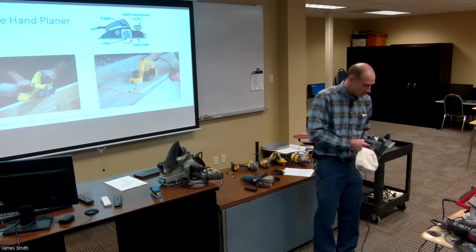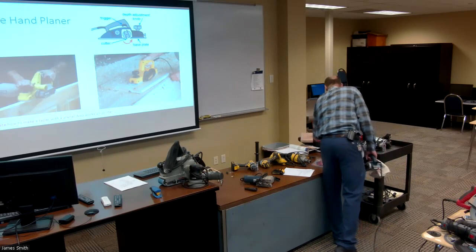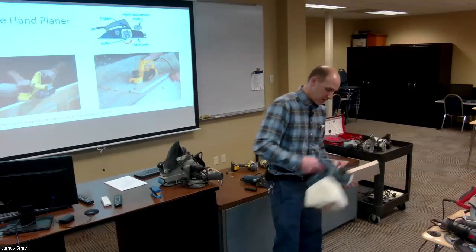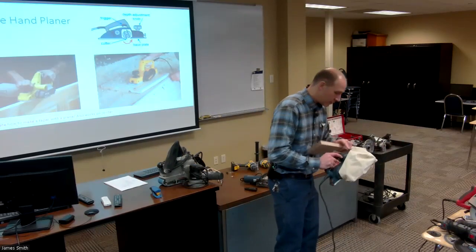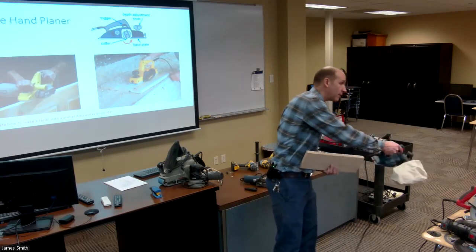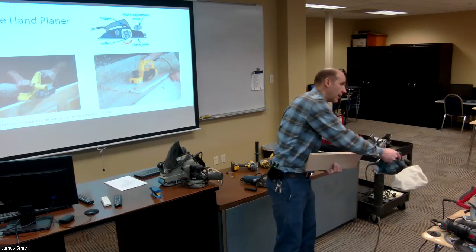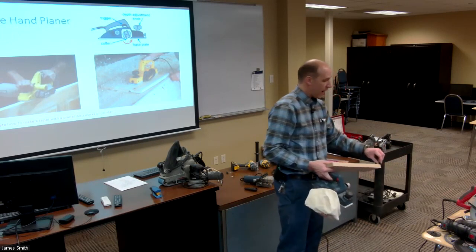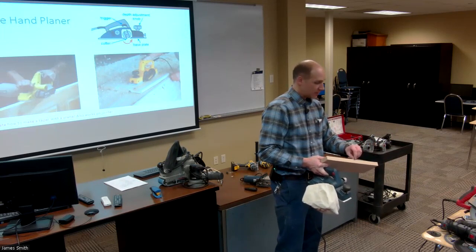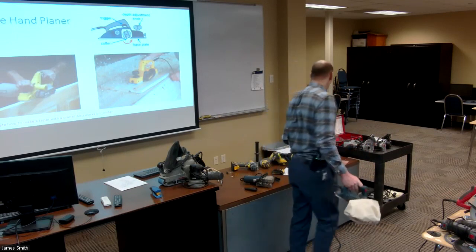Okay. And so these are really good. One thing I do use this for is if I'm on the job site and I need to put a taper into a board, I'll adjust it to a 1/16th of an inch and make a cut, starting right here. I'll move it back a little bit, make a cut. Keep moving it back a little bit, make a cut. Every time I do that, I take the maximum depth of cut on this side and gradually taper into it wherever I introduce the planer. And so eventually I'm going to have a taper. Okay. And so that's a nice way to do that.